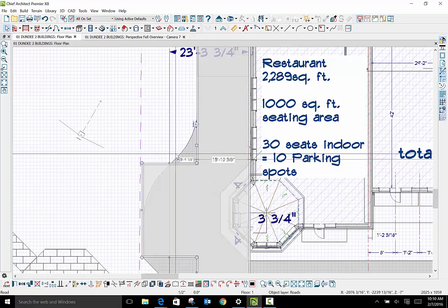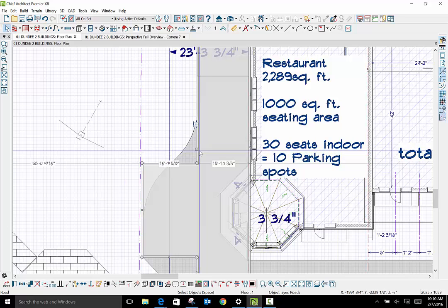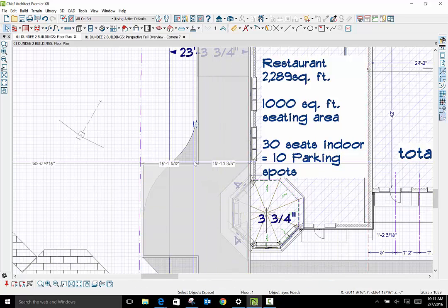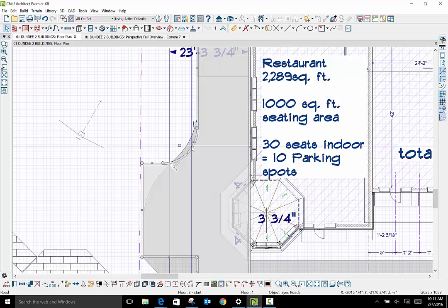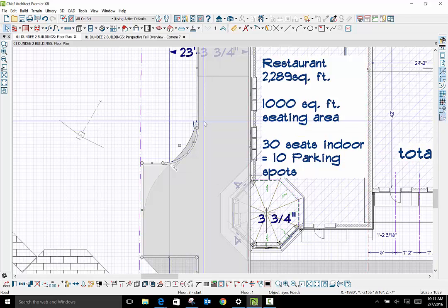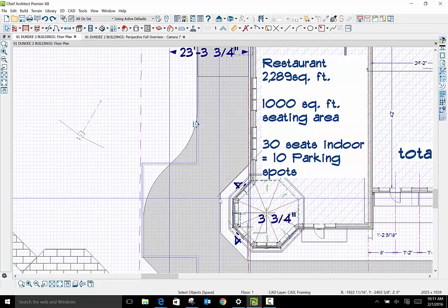Let's go with radius, pick the radius, and let's go with 10 feet. And fillet radius. Pick that. So we want to float that, and our second line will be there. And that's even smaller, so let's use 15. Let's undo. Let's use a 15-foot radius.